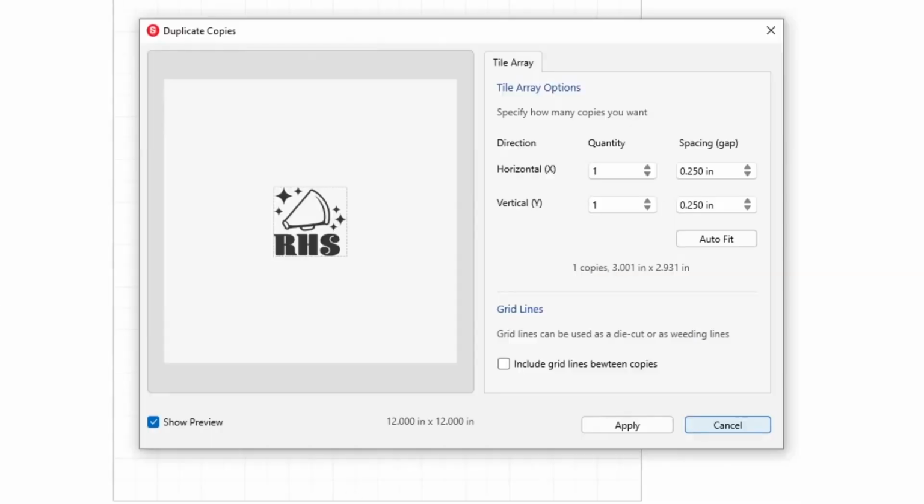Find and hover over the scale icon. While hovering, you'll notice two groups of icons. The first group covers ways to rotate, the second, duplication. From the duplication group, choose the middle icon that says Tile Array and looks like 4 squares.